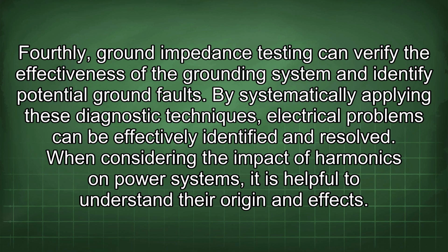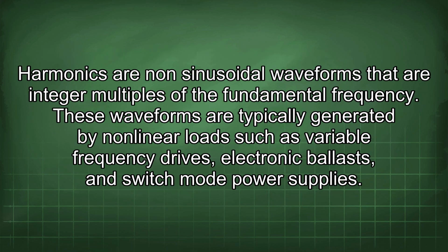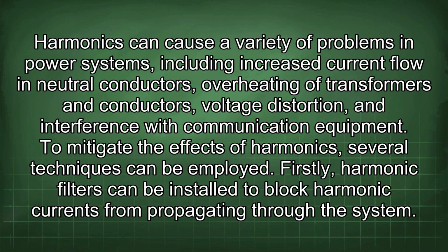When considering the impact of harmonics on power systems, it is helpful to understand their origin and effects. Harmonics are non-sinusoidal waveforms that are integer multiples of the fundamental frequency. These waveforms are typically generated by nonlinear loads such as variable frequency drives, electronic ballasts, and switch-mode power supplies. Harmonics can cause a variety of problems in power systems, including increased current flow in neutral conductors, overheating of transformers and conductors, voltage distortion, and interference with communication equipment.